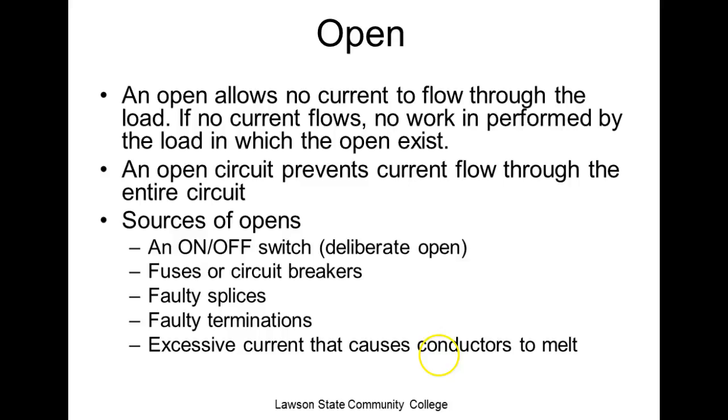One of the things they did in troubleshooting at the Siemens thing was just connect wires to the wrong spot. And that happens all the time. You have electricians going out there wiring up stuff. They take something off and forget how it was wired. They say, I'll remember how to do this. And then they go on a lunch break, or talk to their buddy for a second, and they turn around and forget how that thing came off. And they say, well, it's just 2 wires. And they hook them up backwards. Well, what could you have just done? You could have just created a short circuit.